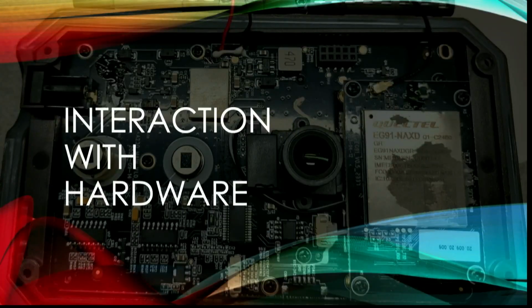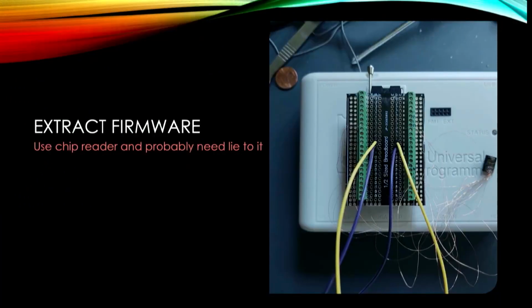So, interacting with hardware. Yes, sir? Is that with the separate VCC power and ground, is that because it's a multi-chip package? No. The one I saw it on wasn't multi-chip. It was purely a NAND flash. I just bring that up because it bit me on something else, and more likely if you're doing this type of stuff, you're going to come across that eventually.